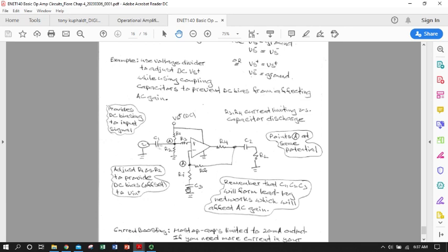So I'm not going to go into the math here, and Fiore doesn't either, but this is just an awareness that when you run op-amp circuits for real, and you did include these capacitors in a couple of your labs, you're going to introduce some frequency dependence, even when you have negative feedback and you have expanded the mid-band range. So remember, that was a big assumption we made at the beginning of Chapter 4, that we were working in the mid-band, and we weren't going to sweat frequency dependence. We would assume that there wasn't any.